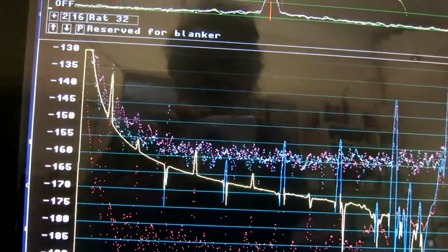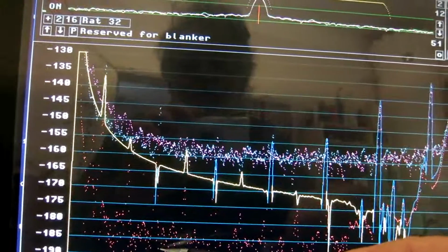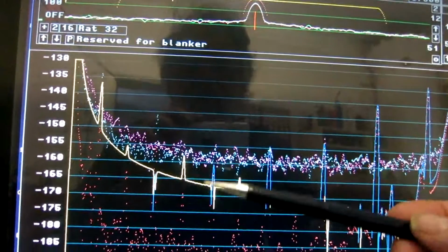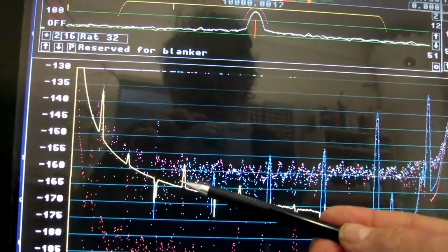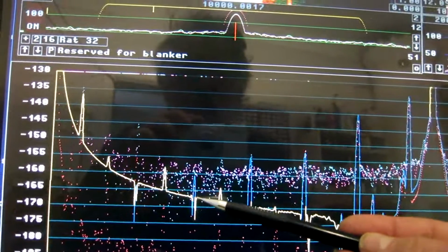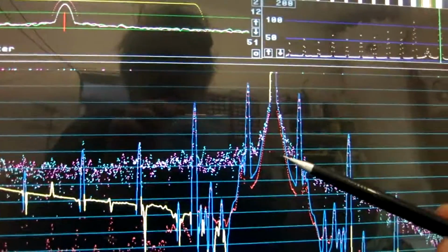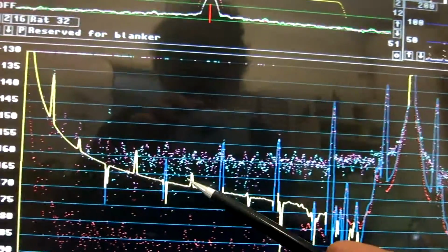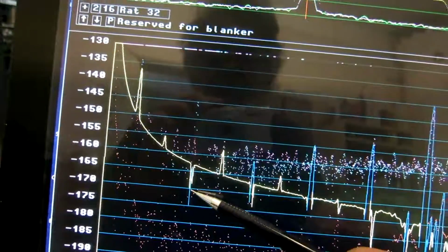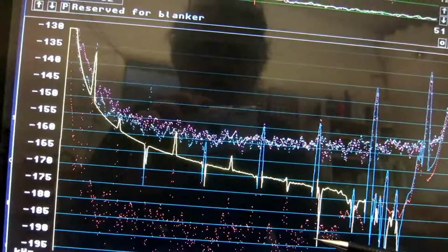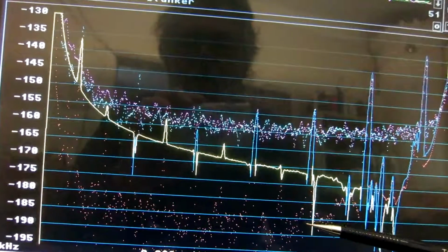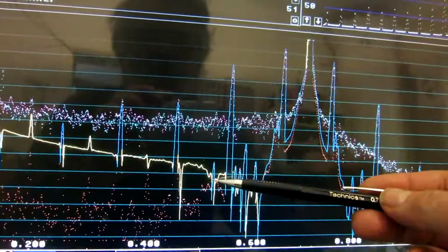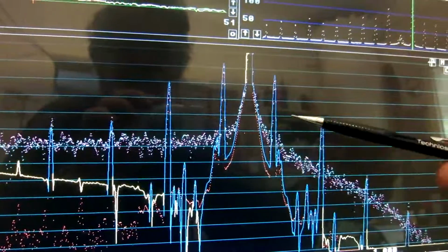The red dots, that is the imaginary part. Adding this into the total, the yellow is the real part when it is positive. Blue is when it is negative. The sidebands of 50 Hertz on the DC components happen to come out with a negative sign, so you can see it comes also here. The imaginary part, which should ideally be 0, is far below the real part, all the way until about here, where the result is no longer significant because of the proximity to the 0.